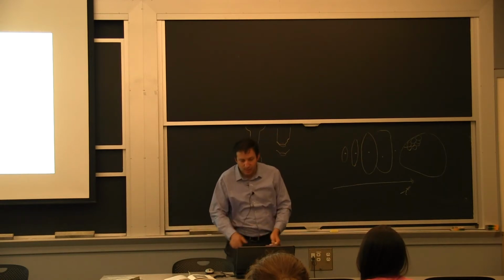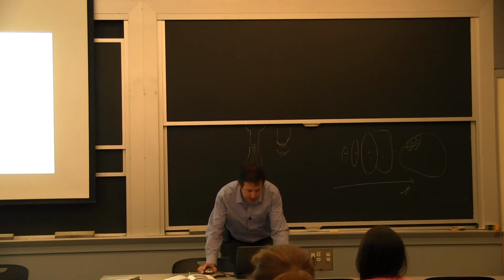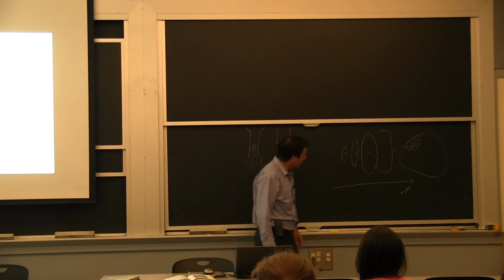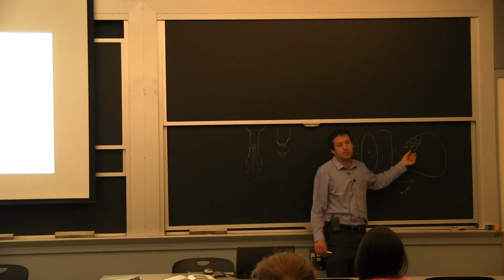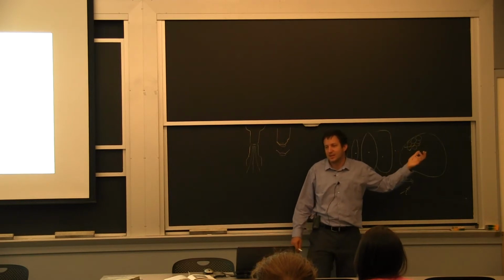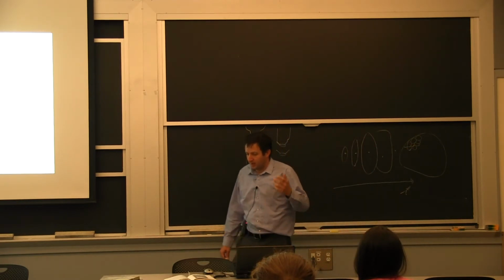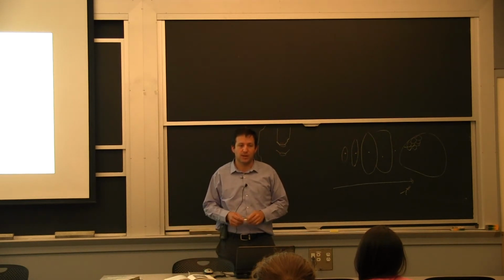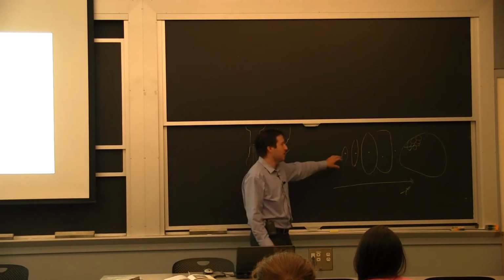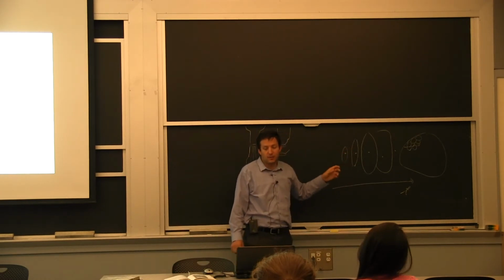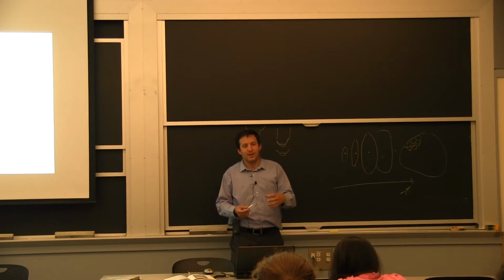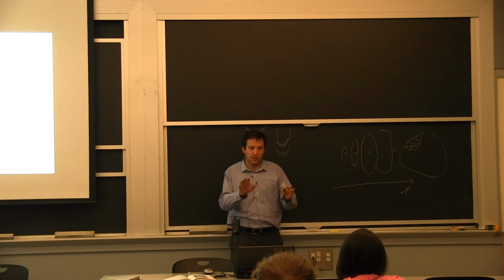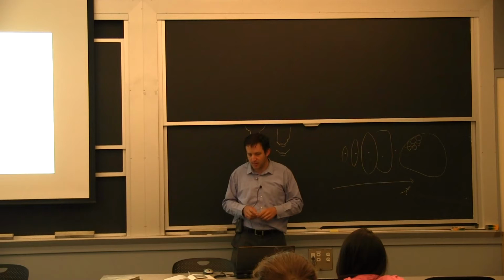So this is a little bit of a summary, maybe more details. A lot of this, when we do failure analysis, this is one of the first things we go and look for. Do we have those dimples? It tells us if the material behaved and failed by an overload, or if there was something else related to the environment or corrosion that caused a crack to develop in another way. Because I could have this sample under the pressure and still have it crack very slowly for environmental considerations. And that's something we'll talk about in the second module of the class.